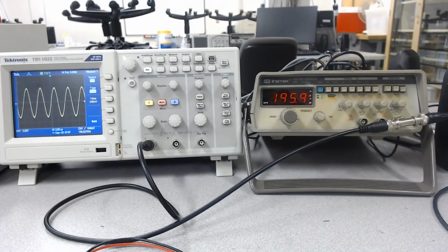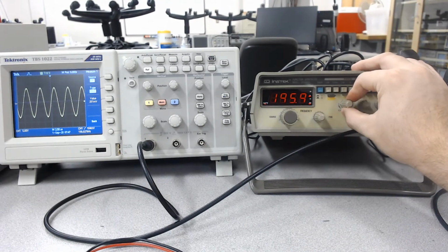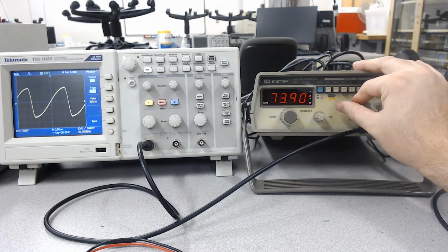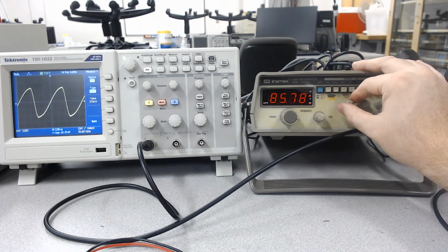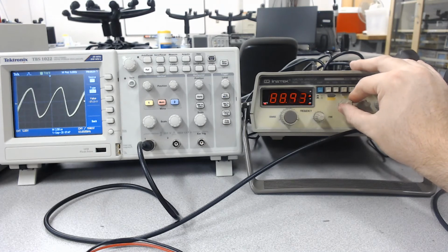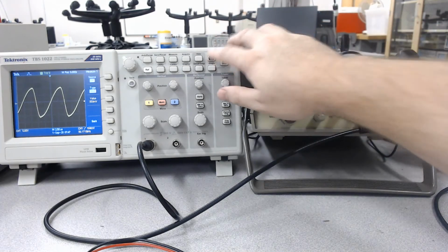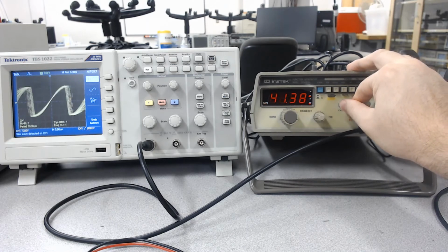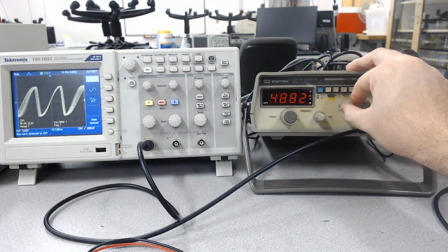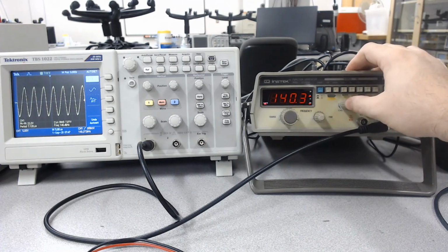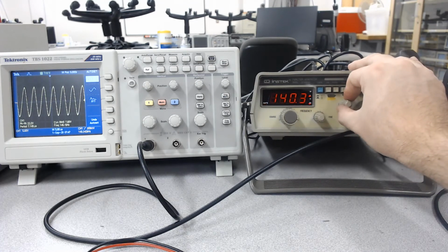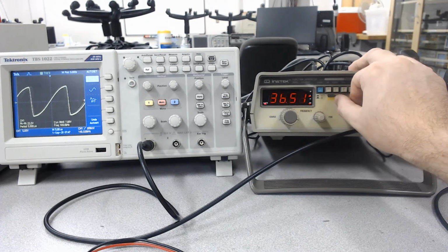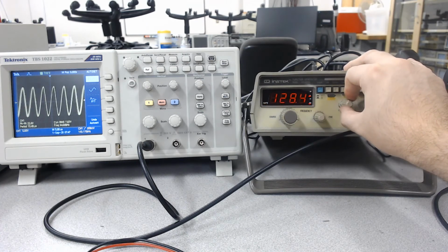So anyways, going back to this, if you take a look at the duty cycle and pull this out, you can actually see it's widening, changing the frequency, but also skewing it to one side. So that's how we can measure that. Let me hit the auto set button, and you can see it skew even more as I switch it more and more. So we'll push that back in. Once it's pushed in, it reverts to normal, although you should know that the duty cycle actually changes whether it's pulled out or pulled in.